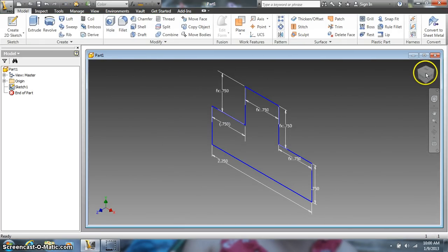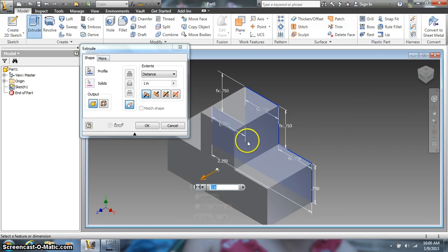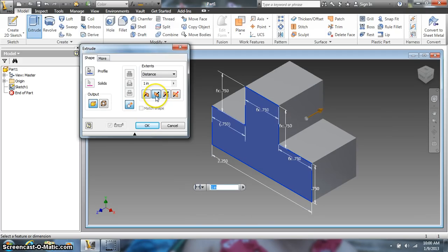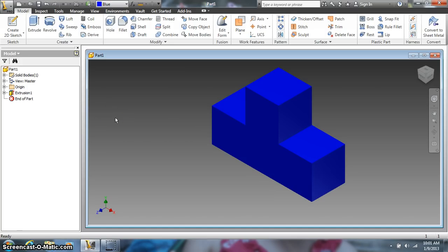It goes in an isometric mode, front, side, top. I'm going to extrude, and I'm going to make it from 2D to 3D. I'm going to select the object. I'm going to extrude backwards the width of one block, 0.75. Last thing I'm going to do is change the material to whatever color I want this piece to be. I'm going to go with blue, and I'm done.